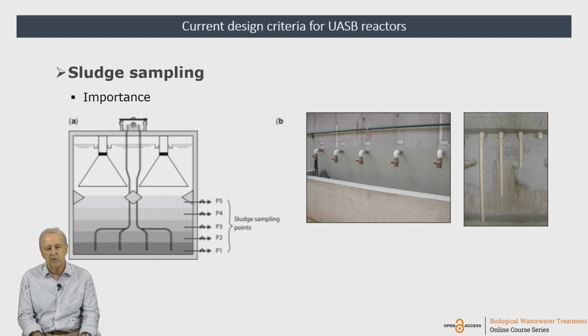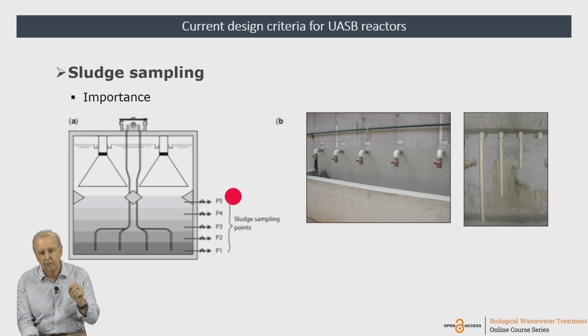And with this, we can check if the sludge load, one of the first parameters that I mentioned in this lecture, is okay, and also compare the concentration determined in the upper sampling point, for instance P5, against another magic number for you, 0.5%. Usually we want to keep the concentration of sludge in this upper sampling point at maximum or below 0.5%.